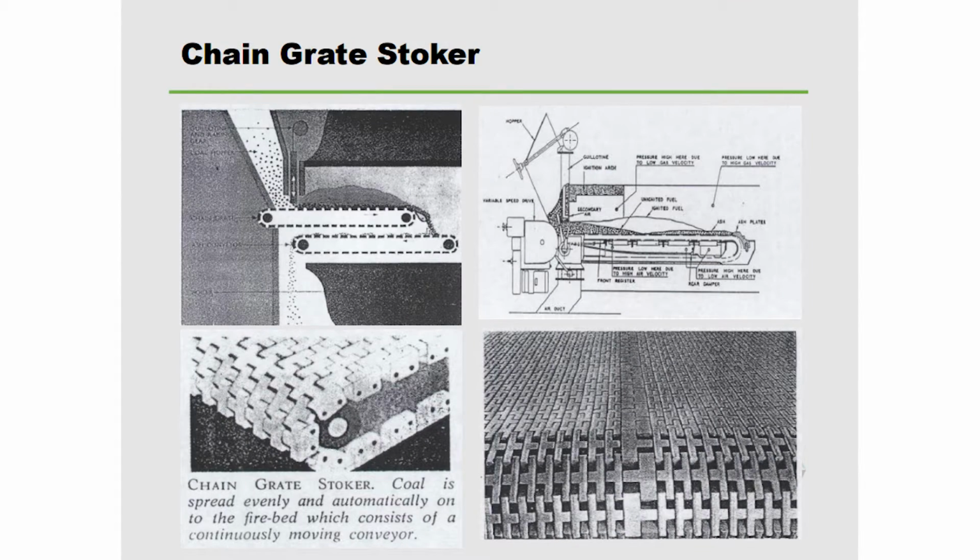Okay, that's the detail on the fact. Another type of the chain grate boiler, the chambered boiler, has the hopper come from here through a guillotine gate to level how much fuel is going to come in, and the coal burning there starts the ignition in that area. That is the front. That is the firing arch.